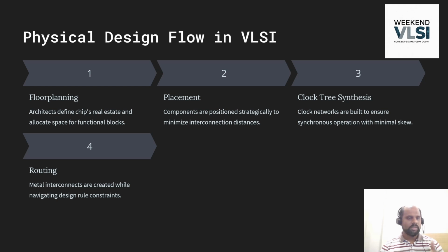And when some signals change from 0 to 1 or 1 to 0, it impacts the nearby signals. This is called crosstalk. Actually, routing is nothing but your RC delays, right? To reduce the RC delays, particularly for the vias, some people use via ladder structures. This will reduce the resistance for the vias.